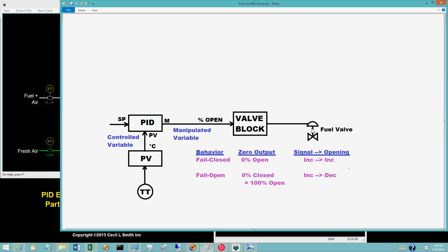On loss of control signal or loss of power, that is supply air, the pneumatic diaphragm actuator can be configured to fail either fully closed or fully open. For loss of power to an electric actuator, a cost-effective approach to provide such behavior continues to be elusive.